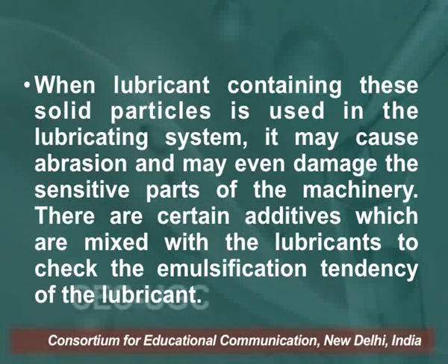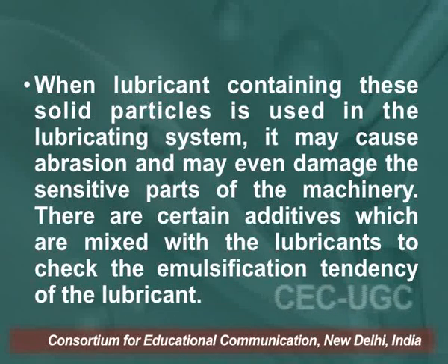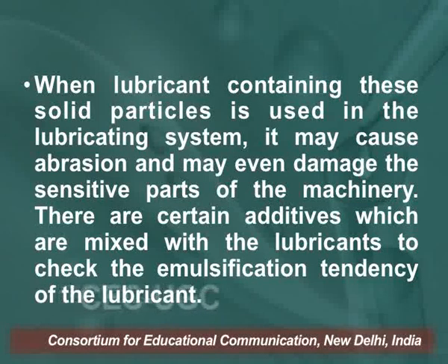When lubricant containing these solid particles is used in a lubricating system, it may cause abrasion and may even damage the sensitive parts of the machinery. There are certain additives which are mixed with lubricants to check the emulsification tendency of the lubricant.